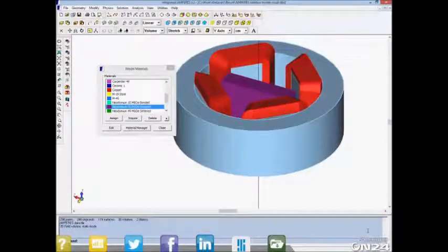So, for example, as the magnet that you see in the center of this quadrupole device rotates, you'll get different flux linkages going through the poles. Depending how fast it rotates, that's going to lead to a dFlux/dt and will induce a back EMF in the coils. So there is a whole circuit dependence because that back EMF will then lead to some current flow and so on.